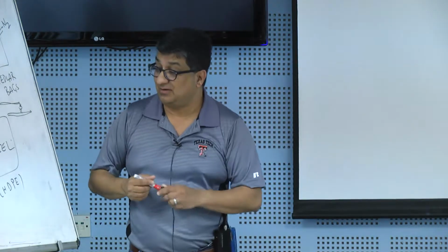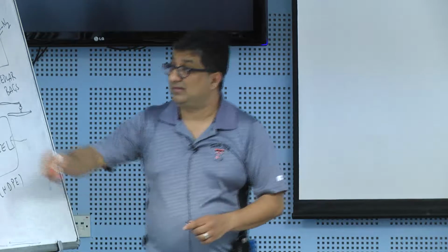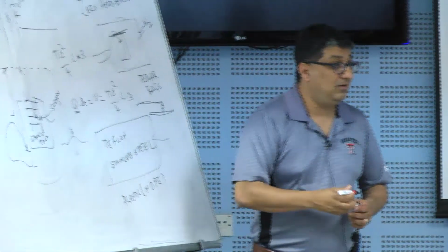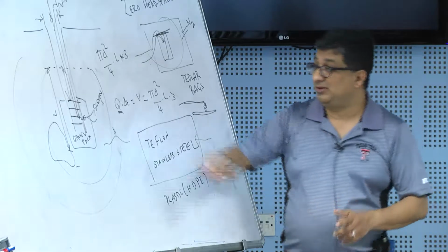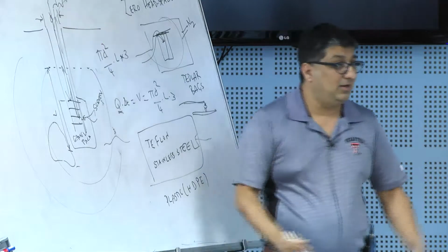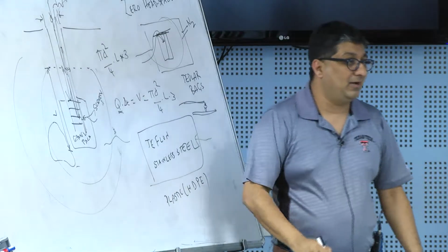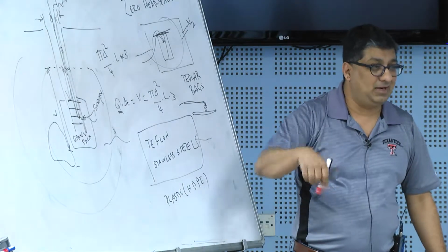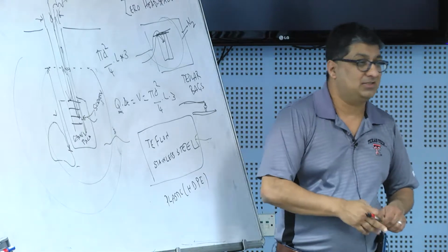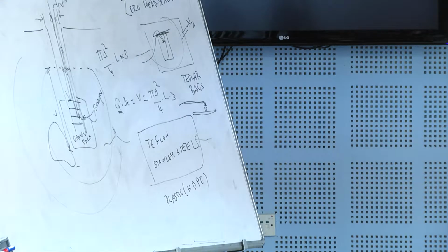Some agencies in the US require you to use stainless steel for your well, which means the entire well is built with stainless steel, because if it's built with polyethylene and I have water coming out of this well, the contaminant may come out of the water and get into the organic high density polyethylene, and that may cause a sample that underestimates how much contamination is there. So there's a lot of time and money spent collecting samples.